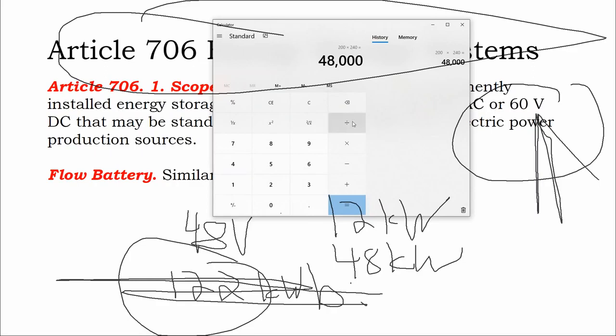If I was trying to draw 48 kilowatts of power, that's my service panel power, but it's going through my battery inverter. And if my battery inverter is drawing off a 48 volt battery bank, going from 48 volts to 240 volts, the voltage is increasing 5 times. Volt times an amp is a watt, and so the amperage is increasing rather substantially too.